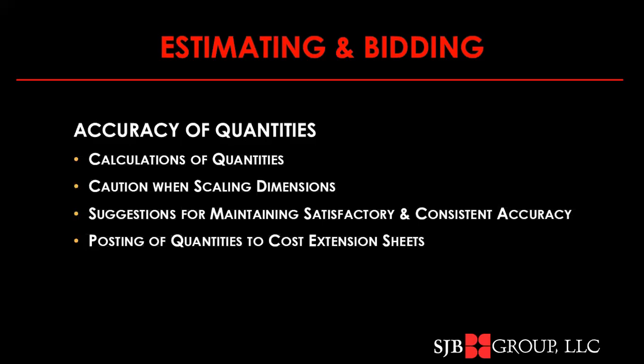You write a lot of numbers as you're calculating your quantities. When you get to the answer that you're going to carry to the costing sheet, probably want to circle that number. You're going to want to adopt standard code and marking systems so that the items can be checked by you and others.